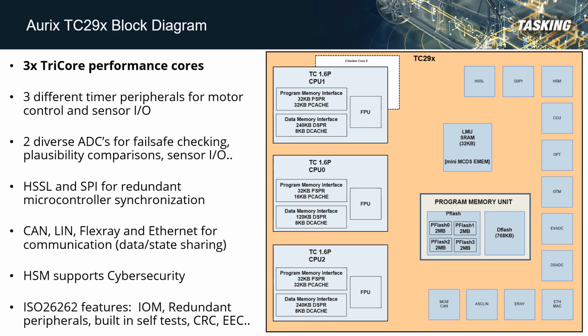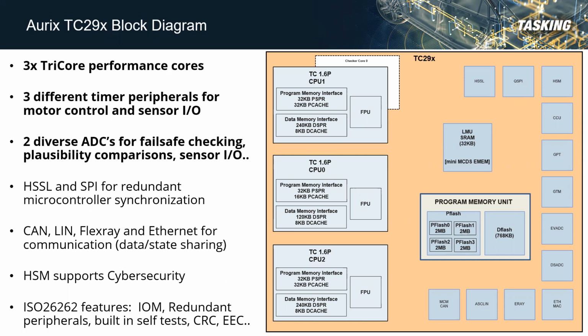So in this particular application, we will focus heavily on the 3 tri-core performance cores. We will look at the different timer peripherals for motor control and sensor I/O, and then we will look at the different diverse ADCs for fail-safe checking, plausibility comparisons, and sensor I/O.